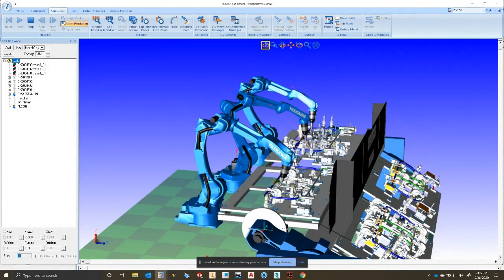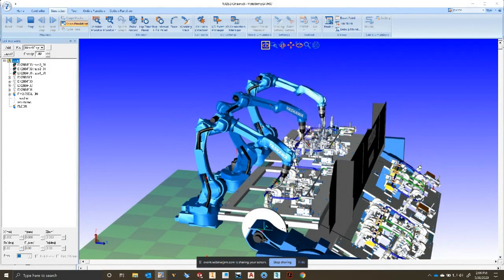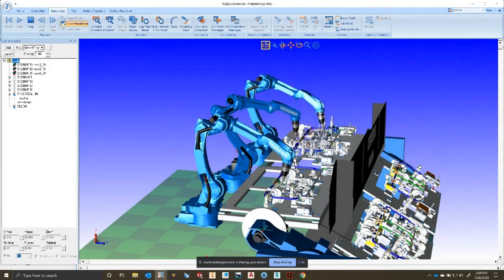For offline programming, the advantages are, let's say your cell is under construction and you need to have programming done. You don't need to wait for the cell to be finished. You can just start programming in simulation, and then you can pull the job files and the other data files out and put them in the real cell, and then do some basic touch up, because there'll be some variance depending on how it was assembled, or maybe the angle of your torch if you're using welding.